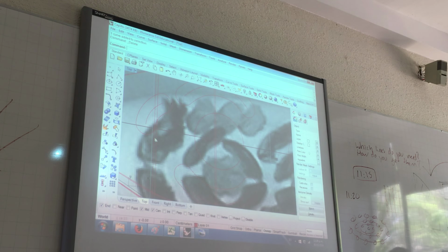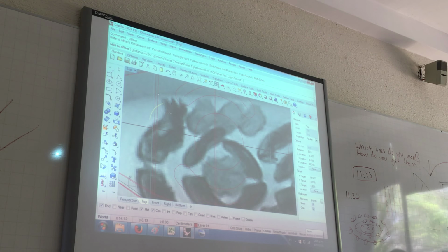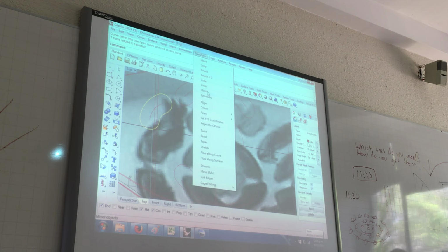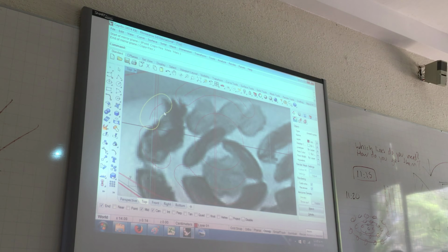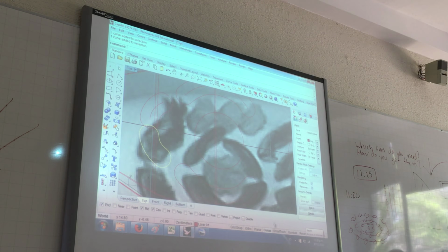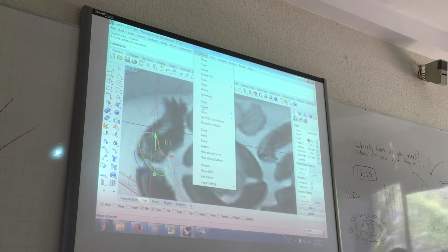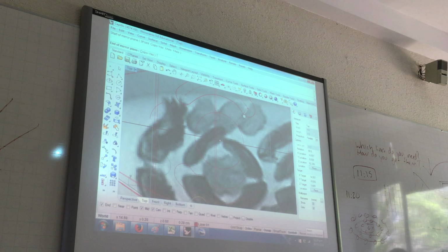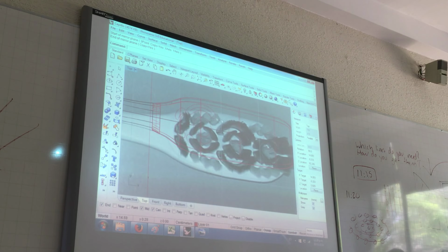Okay, I'm going to repeat this. So this has to be smaller. So I'm going to turn the control points on. I'm going to scale it. Curve, offset, both sides, there, and I'm going to mirror it. And I'm going to move this and this a little farther apart. I'm going to mirror it. Transform, mirror. There. So imagine that I did the same thing with all of them.